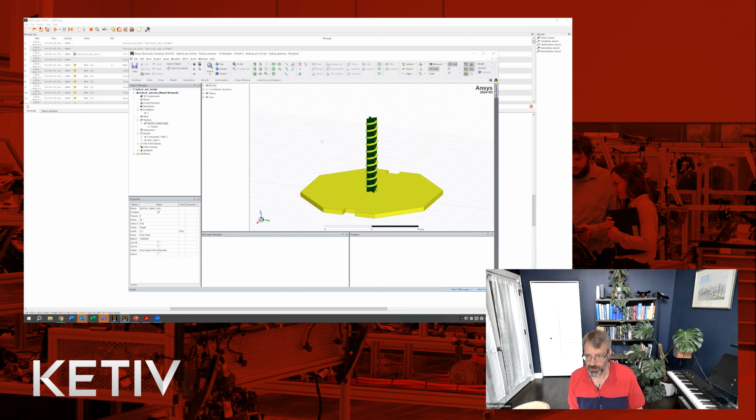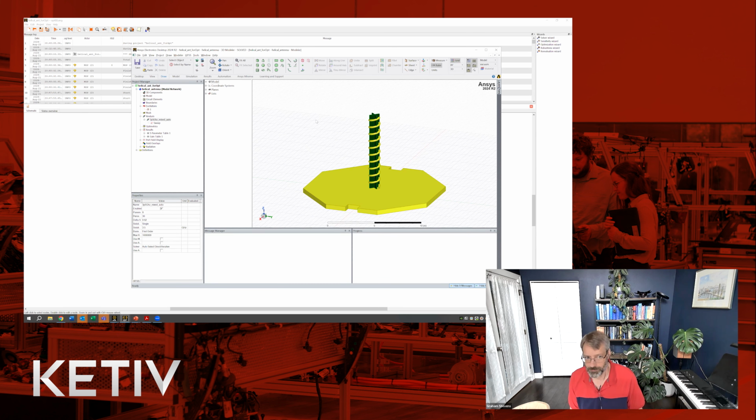Typically for the HFSS model that you're feeding into Optislang, you also want to make sure that there are no Optimetrics analyses here, because of course those would force you to run parametrization of 10 times or 20 times for each run that Optislang is doing, and we don't want that.